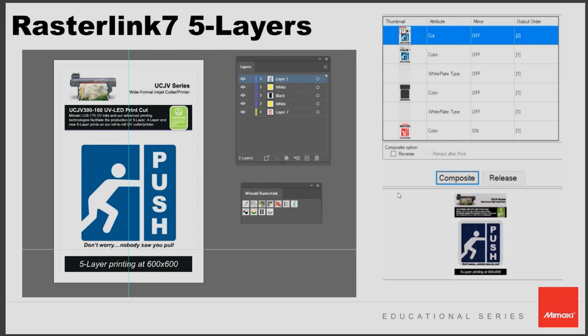And then we also have 5-layer printing, which again, our roll-to-roll UCJV 300, UCJV 330, both can print up to 5 layers. With 5-layer printing, you have a true double-sided image, or an opaque double-sided image, which means you can have two different images on both sides. So what it does, it prints color, white, a black layer in between for the blockout, another white layer, and then color. So that way, if you hold it up to the light, the other image does not shine through the middle because of that black blockout layer.